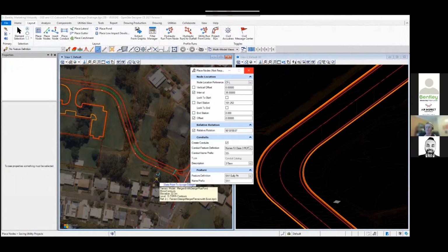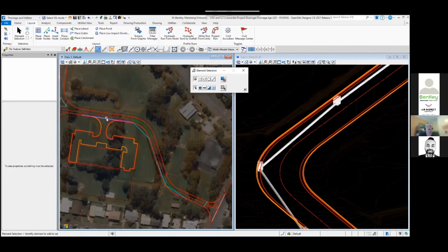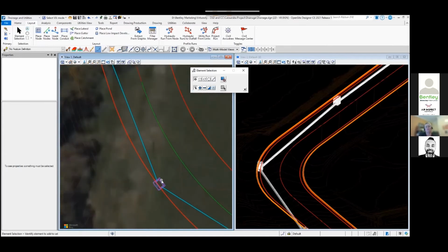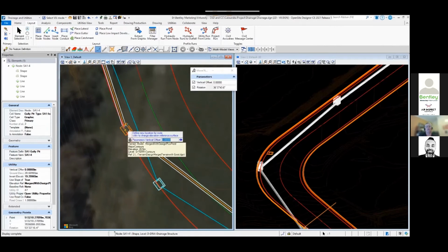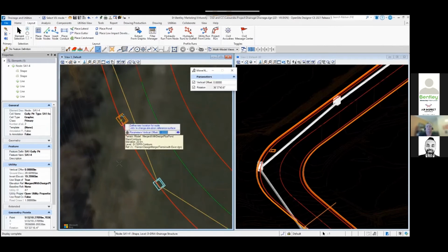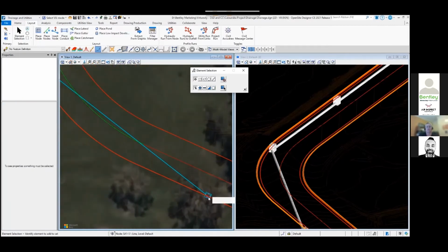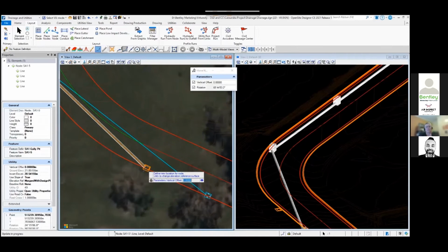We go and select that gutter line. It'll go through now and place those pits at a predefined spacing, or in my case, I think I made them 35 meters apart, and join those up. Now, once they're in there, you can modify them, you can move them. And again, they're fully parametric. They understand that they should be perpendicular to the control line, which is the center line, so they'll adjust accordingly. And I like placing these roughly at the tangent points there.